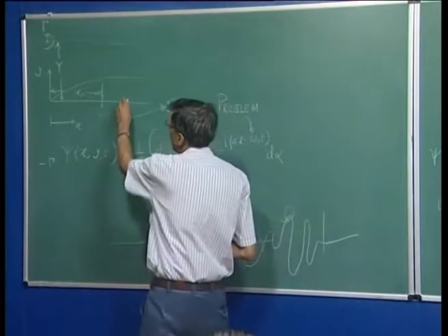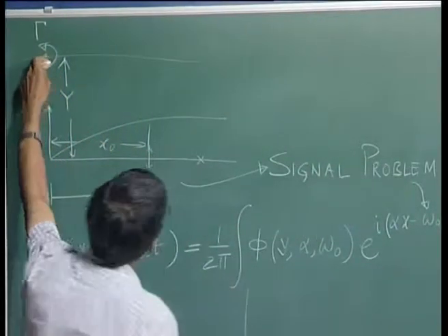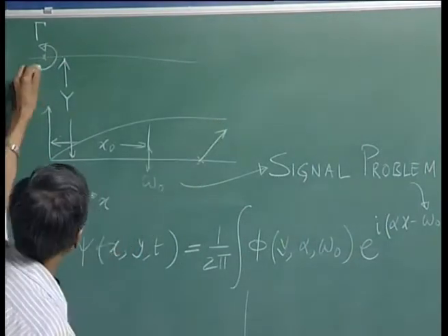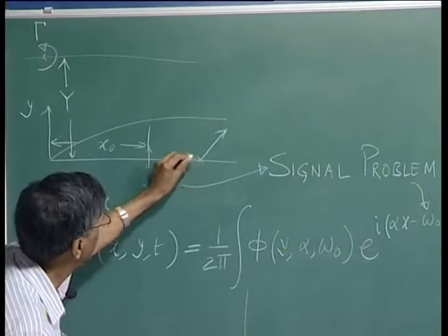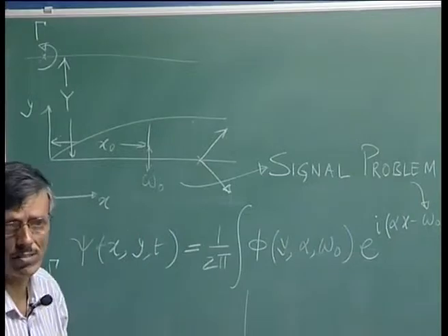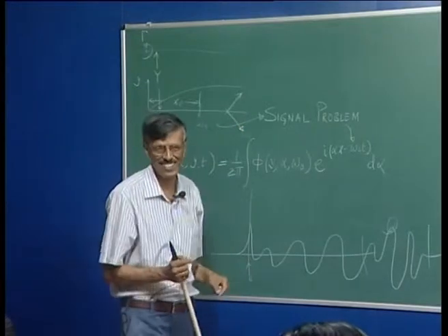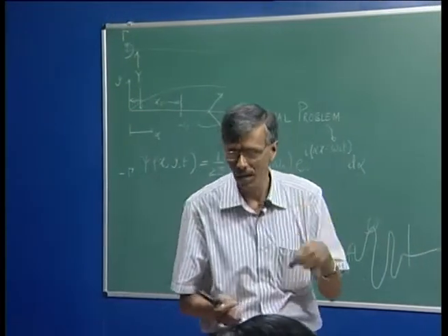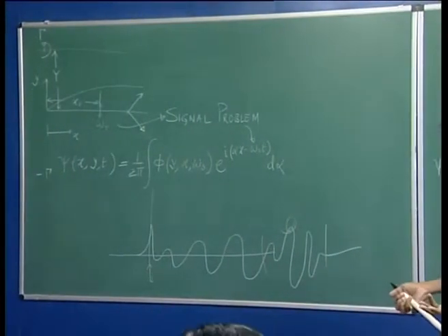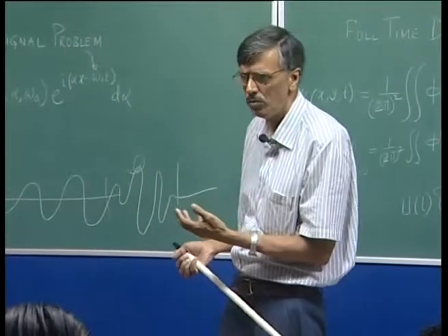So, that if I look at any point on the wall, this will introduce a velocity in this direction, and this one will introduce a velocity in this direction. So, that the wall normal component cancels and the two provide a slip velocity. You see that this is a description of the inviscid way of looking at this vortex. Okay.